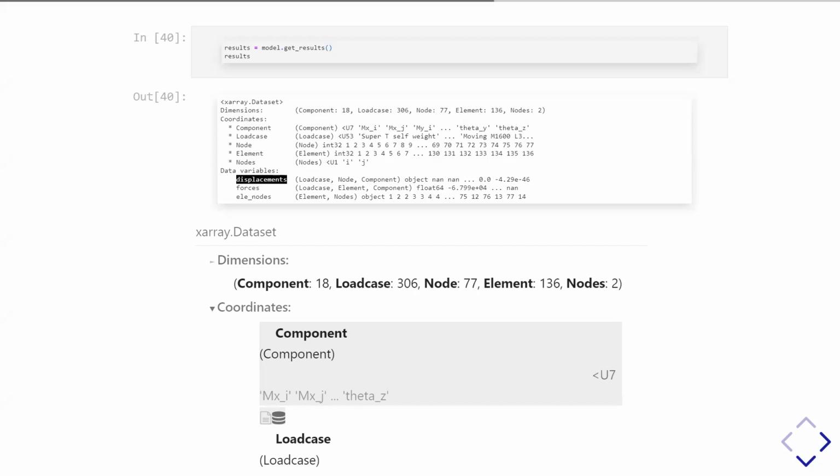All of them get stored in the results object. All forces get stored too: all your bending, torsion, shear, all those results of each element, or for displacement, each node, is all stored within results. So all you need to do is just extract them, and next we show you a bit on how you can extract.